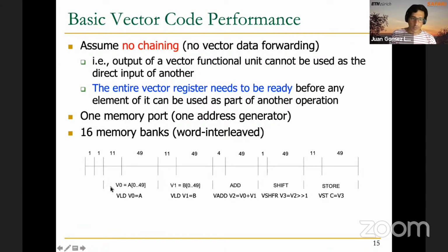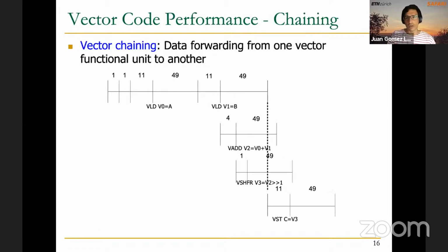And then in the execution of these individual instructions, we have first the whole latency of the first operation, and then after one cycle, we start receiving the result for the next lanes of the vector, or the next elements in the vector. In total, this execution takes 285 cycles, which is already much shorter than what this takes to execute in a sequential processor, as you can calculate yourself.